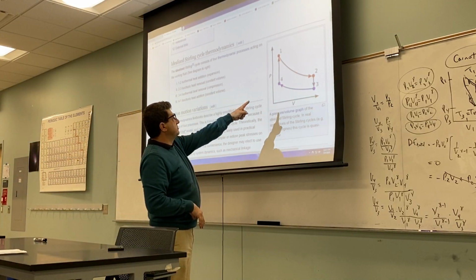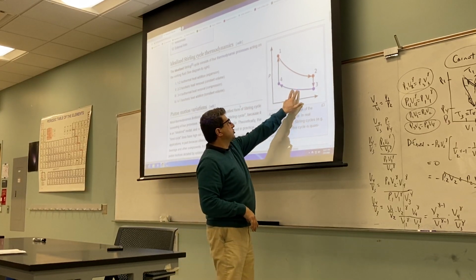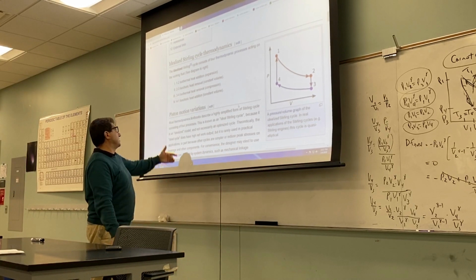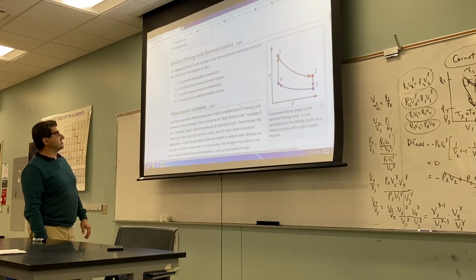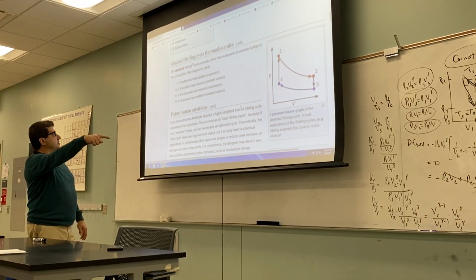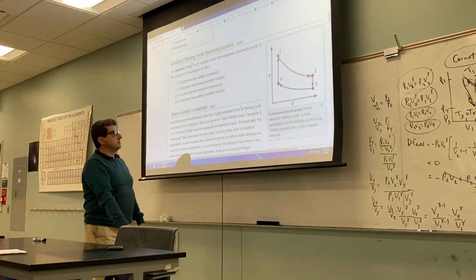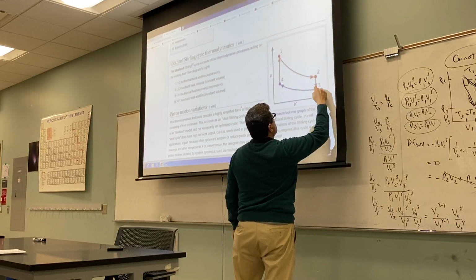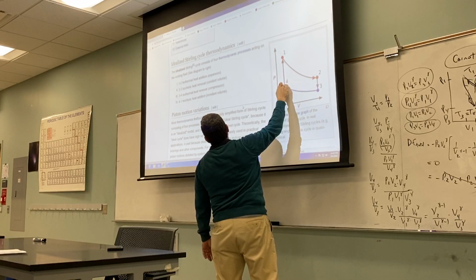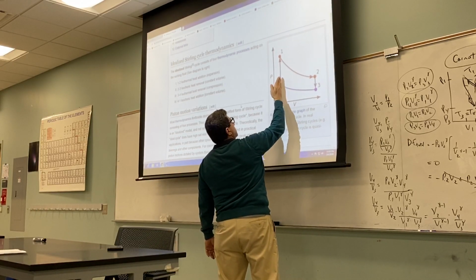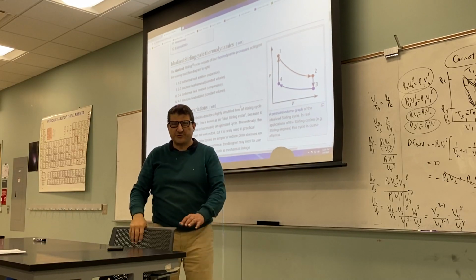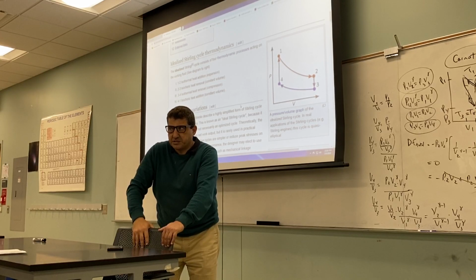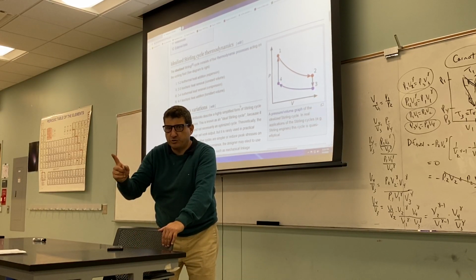It's a constant volume. I'm just not sure, is this isothermal or adiabatic? Well, let's read it. Isothermal heat addition, isochoric heat removal. So here you're adding heat, you're removing heat. Here isothermal compression, okay? Could we derive the equation for the efficiency? But you know what? It's simpler than adiabatic because we don't have PV to the gamma to worry about.